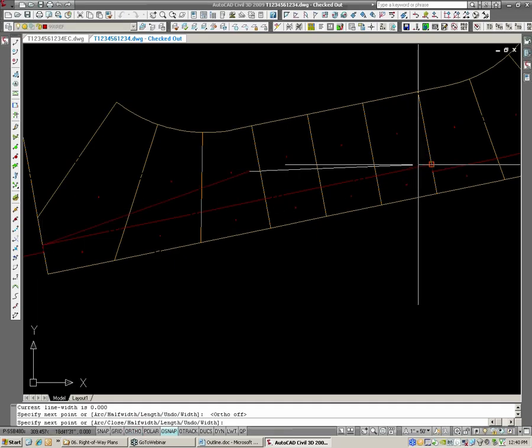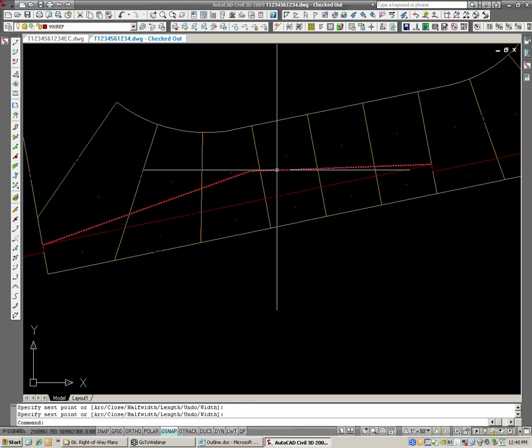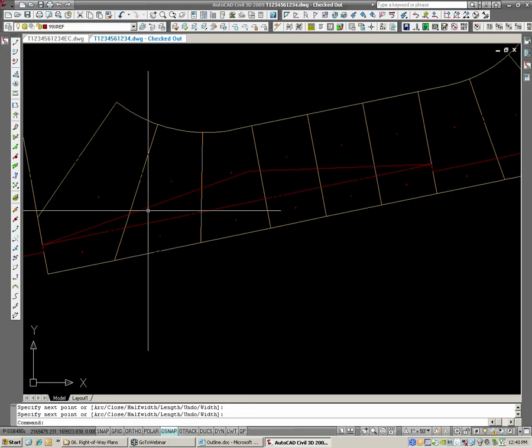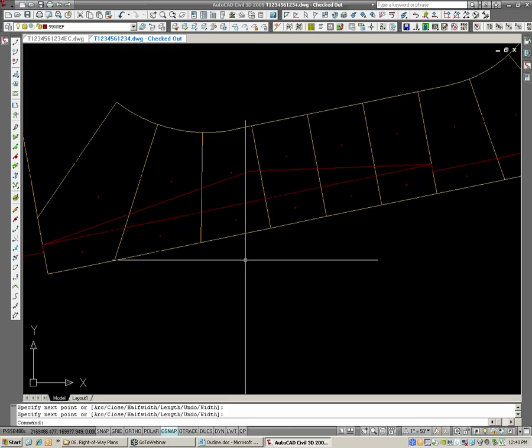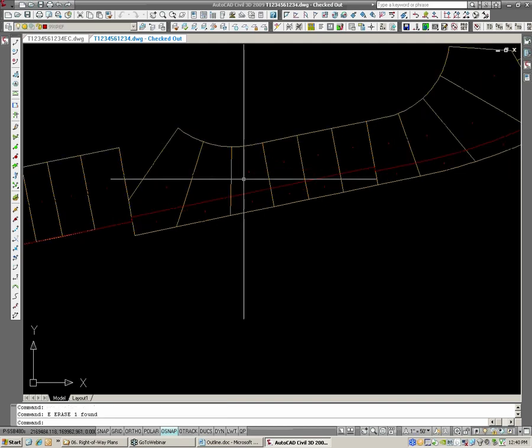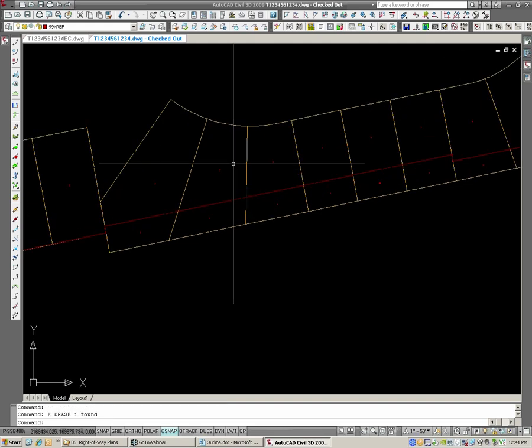You're tasked with doing part of the right-of-way take. Say somebody in the corridor model is designing and moves this to a further right-of-way or puts a jog in it like this. It will update automatically in your parcel drawing. And all your labels generated from this point forward will automatically change. And the cross sections that somebody else did, they'll change as well. So you get that data linking between these files, which is really the whole point of Civil 3D to begin with.